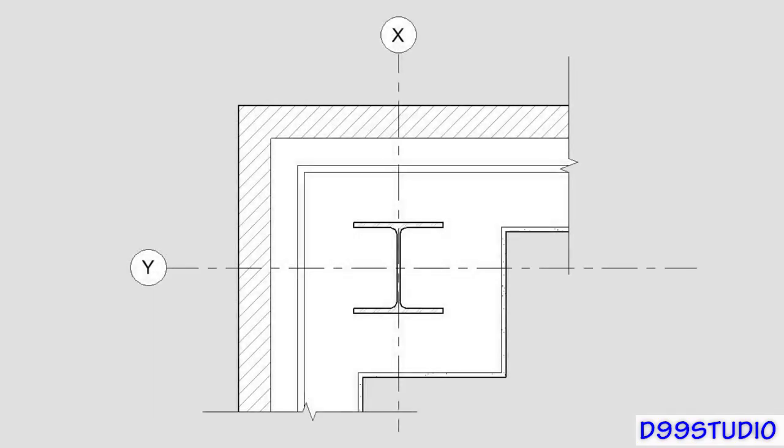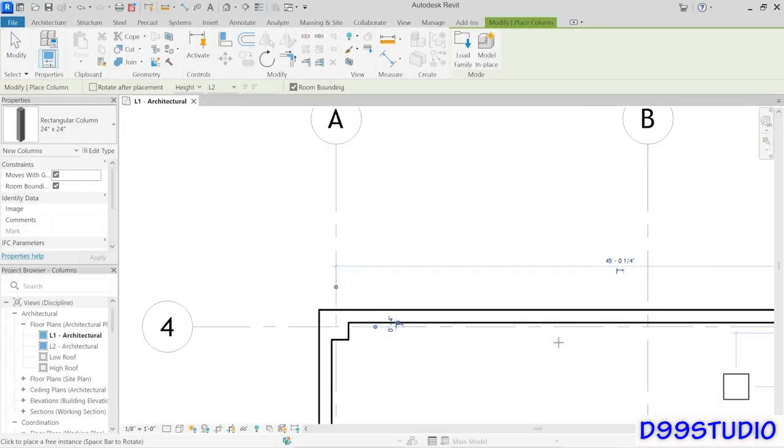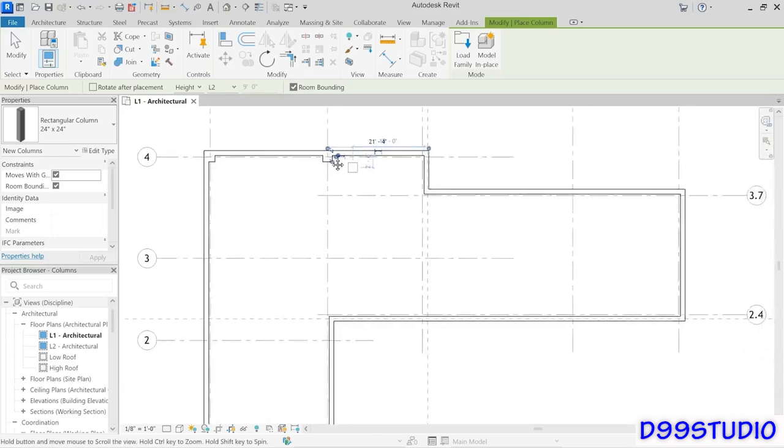So later, as the project progresses and we add more detail to the exterior walls and so on, the fact that we have this embedded column in here, notice that it's going to continue to embed in those walls and even take on the surrounding materials of those wall assemblies. So that's a really powerful benefit of this merge feature that we're getting really for free. All you need to do is just click near a wall and it will automatically take on that behavior. So that's just something that architectural columns do on their own.